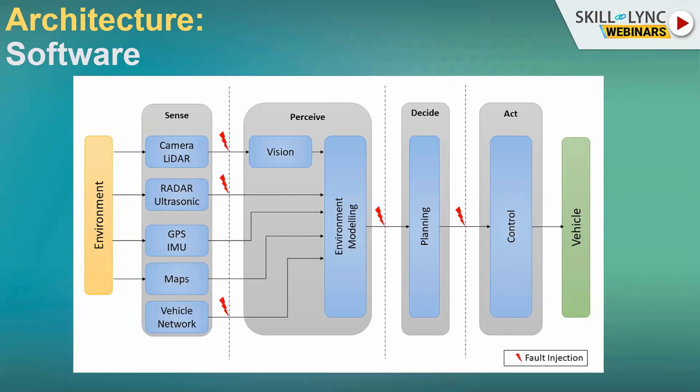And once this path is predicted for the lane change, then comes the final layer, where the actual control signals are produced. We have a reference that I have to follow this path, and the control layer is what actually makes the end effect. Calculate the steering angles, calculate the amount of acceleration that is needed in case of overtaking a car, or in another situation, let's say the car in front of us starts to brake, then we have to judge this and accordingly also apply brakes so that we avoid collision. So this is what the software actually looks like.